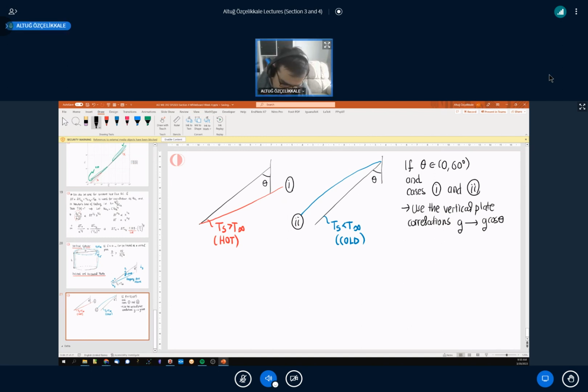But then there is the top and bottom of the plate. For instance, when we have a hot plate, there's not going to be a boundary layer particularly forming here. Instead, parcels of fluid are going to, when the boundary layer starts forming, form those plume-like structures, and they are going to evacuate the boundary layer and go like that.